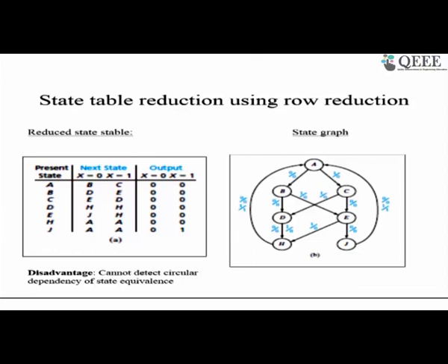Which flip flop gives the better performance in an FSM? JK flip flop based realization leads to fewer gates when it comes to actual implementation. Although the design is complex, JK flip flop based implementation gives a more compact circuit. But the performance, meaning how fast it is, depends again on the gates, and in terms of speed JK may also give better performance.